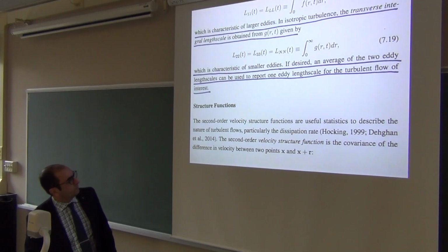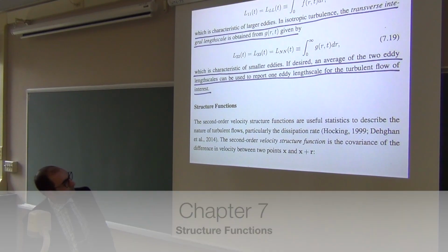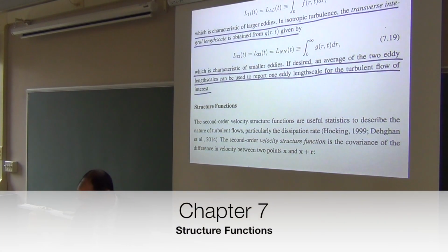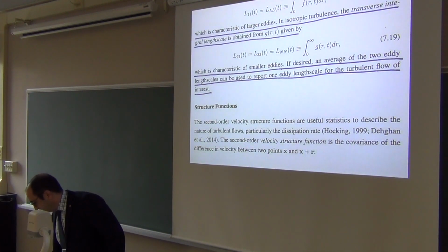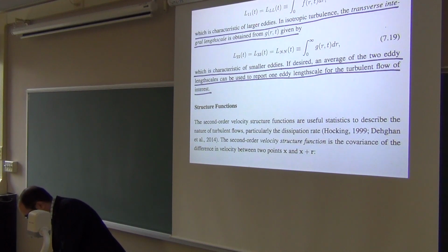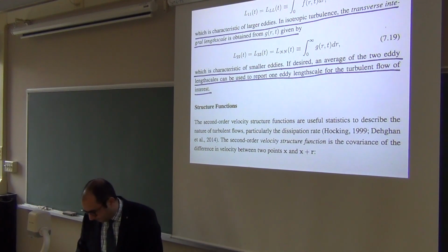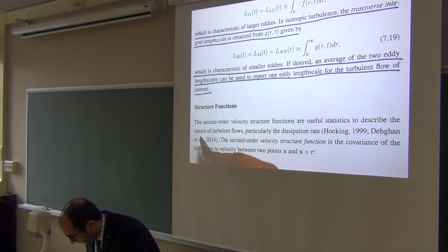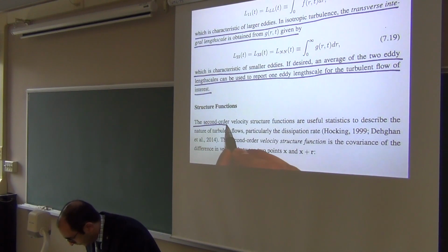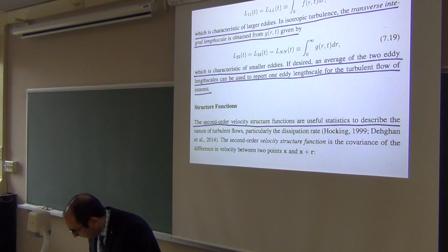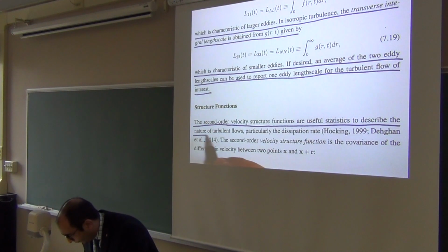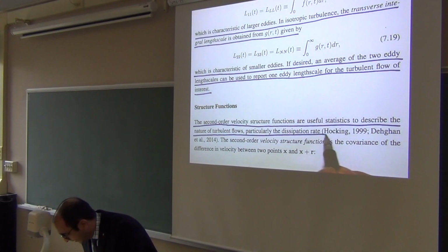Sounds good. The structure functions. Again, extremely useful and practical for model development. And we are in good shape. The second order velocity structure functions are useful statistics to describe the nature of turbulent flows, particularly the dissipation rate.